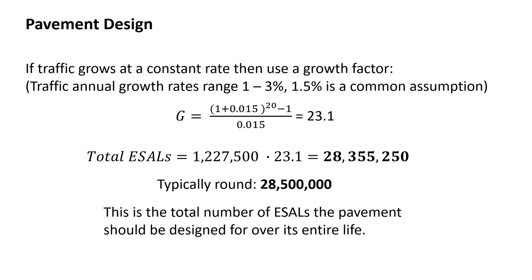Now, maybe they'll tell you, here's what our normal truck is, and then you calculate it once, and use it for every single truck that goes through there. But more commonly, you're going to be working for public agencies. Whatever state you're working in, they'll have their average truck ESAL value. And this is how you end up with it. So now we know what to design for. Now we know what to plug in. This is that W18 number in the great big equation. This goes into there.